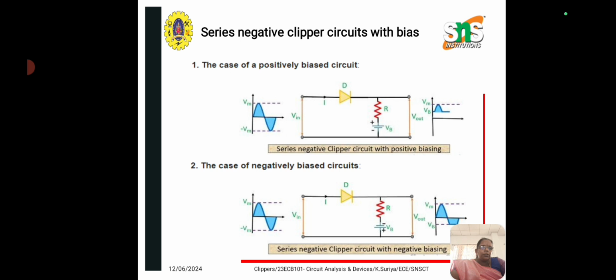However, the battery potential causes the diode to be in reverse biased condition. So in the beginning, the battery potential is higher than the supply voltage, causing no current to flow through the circuit at that time. But when the positive half supply voltage exceeds the battery potential, then the diode becomes forward biased and starts conduction. Hence the signal appears at the output.